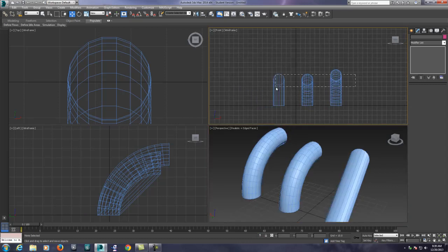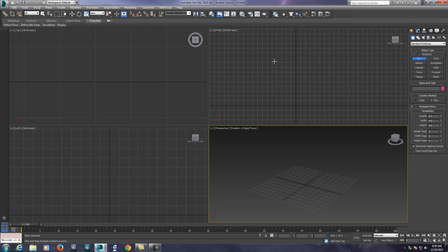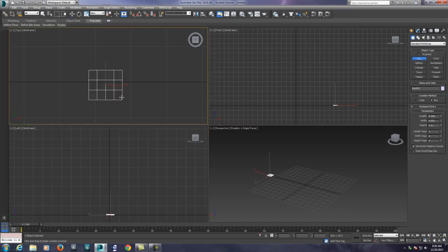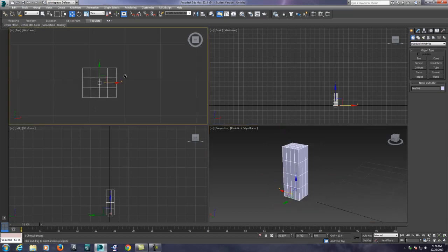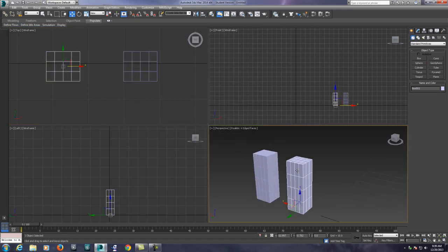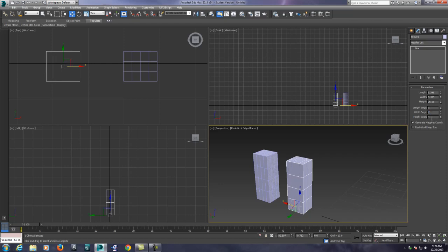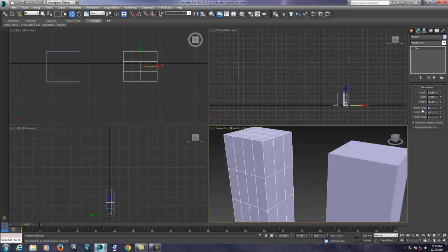All right, for my next demo, and I'm going to start moving pretty quickly here. Now that we have an idea of how an object modifier works, bend, of course, I'm going to show you another one here, and that is we're going to look at the twist modifier. And it's the same idea here. Just to give you a rundown, we'll do 2 different boxes here. And one box I'm going to completely remove all of the segments there. I'll take it down to 1, 1, and 1. Where the other one I'm going to go ahead and increase the segments to 5, 5, and 5.